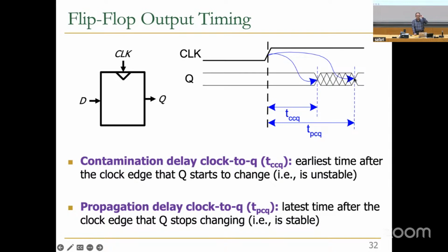Yes? Yeah, one question. Where is Q in this metastable state? What's the reason for it? Well, because of the way that we implement the flip-flop. For example, it is two latches, a first and a second latch, and each latch, for example a D latch, has several NAND gates.